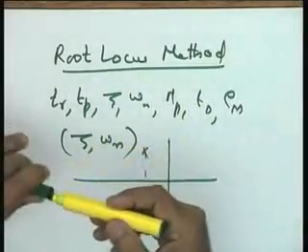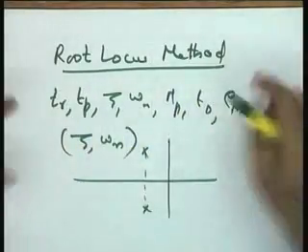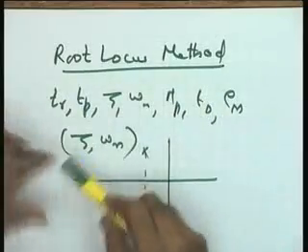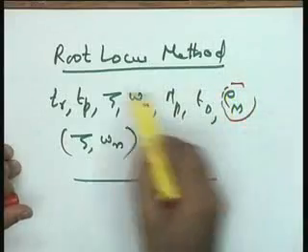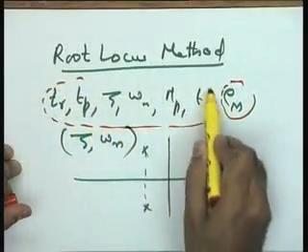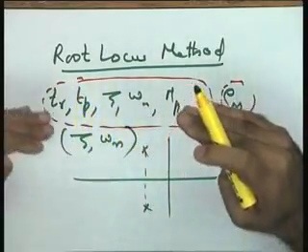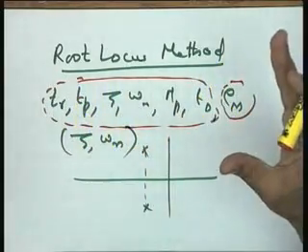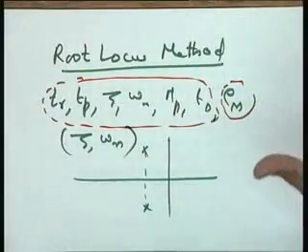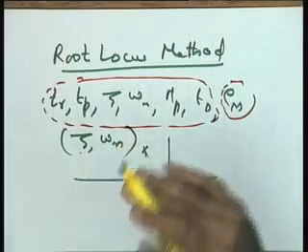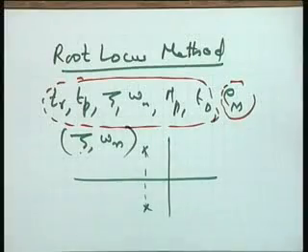So can I say that actually the total performance which I have given you in terms of all these measures, as far as the transient part is concerned, steady state part is separate. As far as the transient part is concerned, this transient part can appropriately be translated into a pair of dominant closed loop poles. So, if you have a large order system, a system higher than second order, in that particular case you have to see that all other poles should become insignificant, so that these zeta and omega n have got the meaning in terms of peak overshoot and settling time.